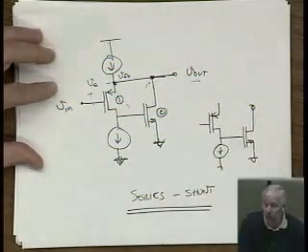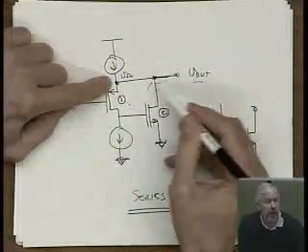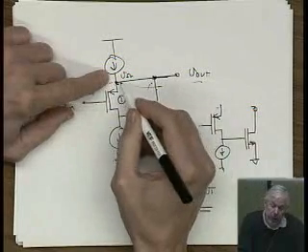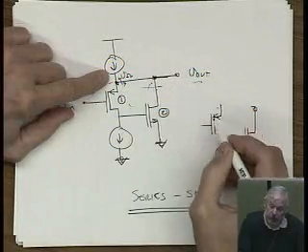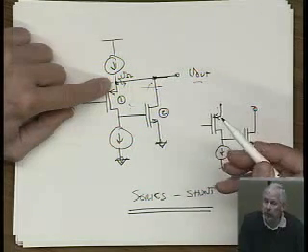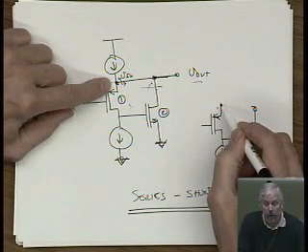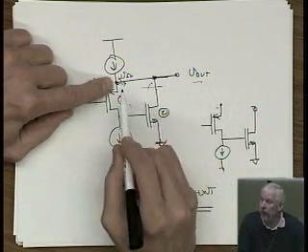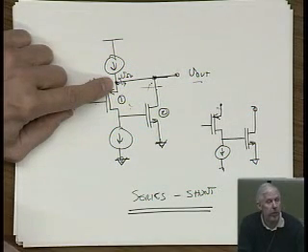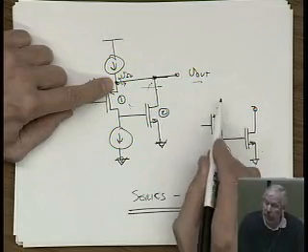Okay, now, we've got to do something with these two nodes here. This is the feedback network. So what do we do looking into the feedback network? That's what we want to tie. So this is the loading effect of the feedback network in some sense, right? So what do we do on this side for a series shunt feedback network? What will we do at this point? How do we model the feedback network from the point of view of looking from the basic amplifier?